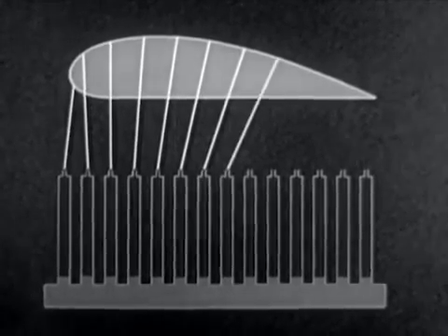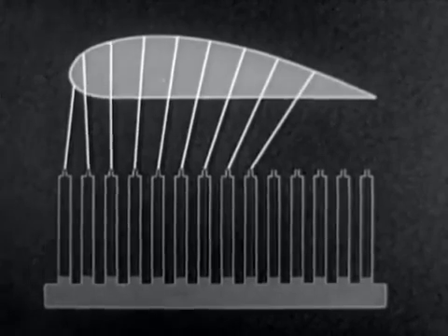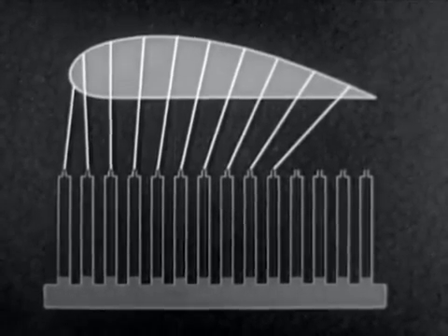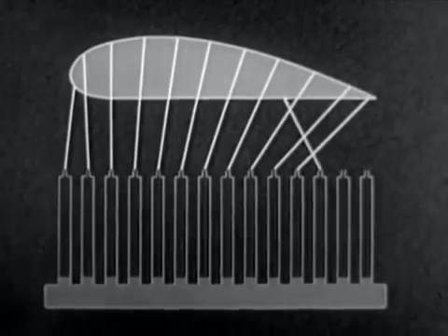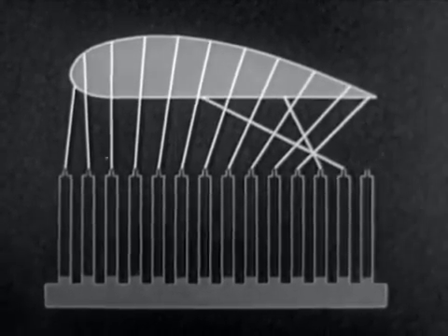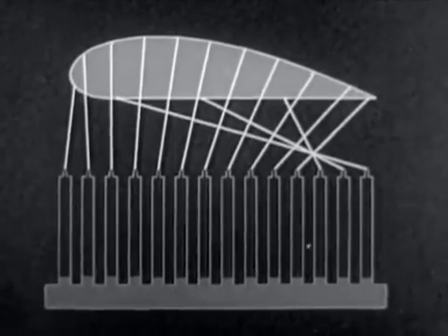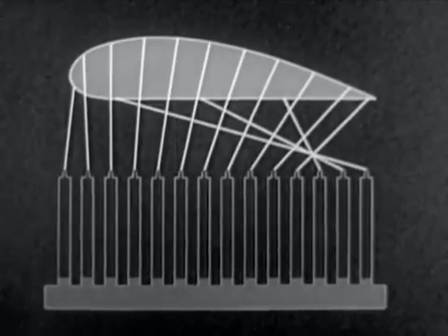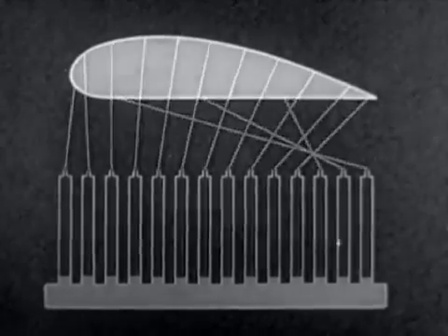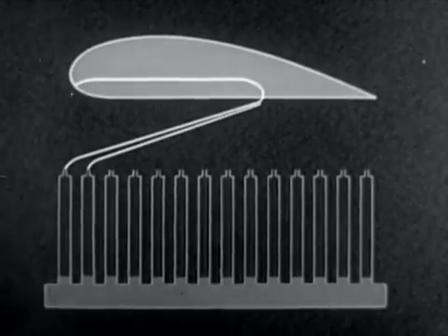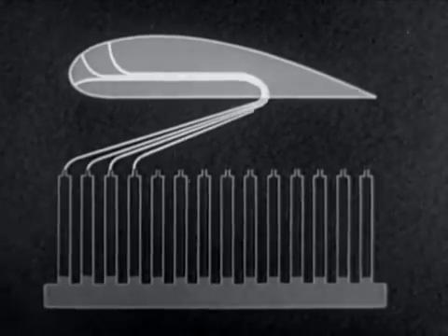The majority of these test points are located on the leading edge and upper surface. Relatively few are placed on the lower surface. Of course, this is only a schematic representation of the connection. In actual practice, tubes run from the manometers through an opening and inside of the airfoil to the test point.